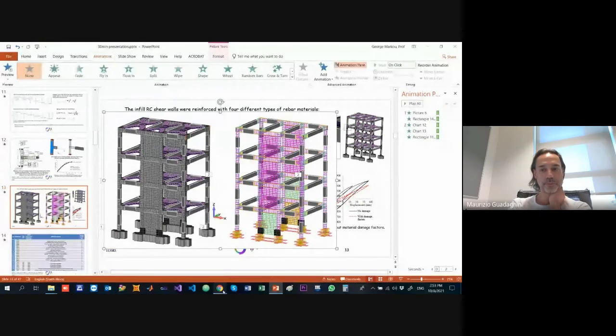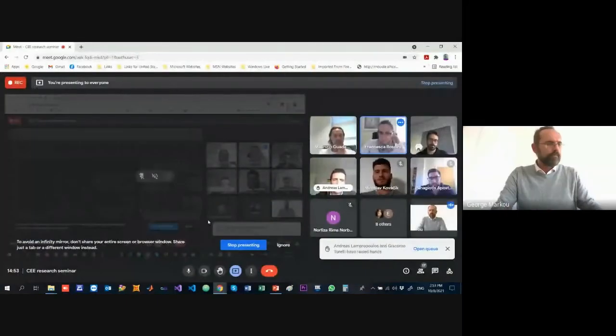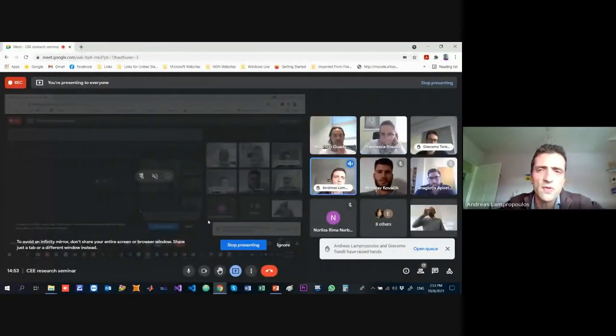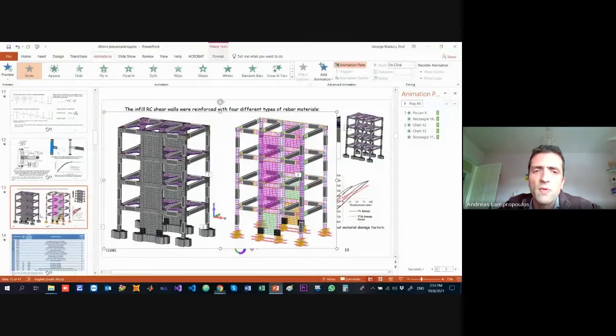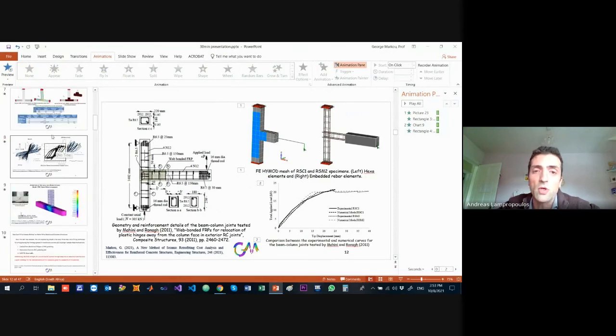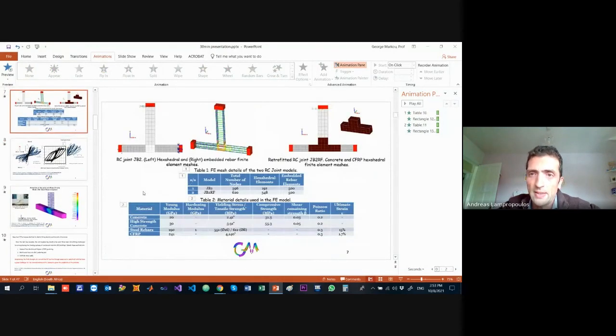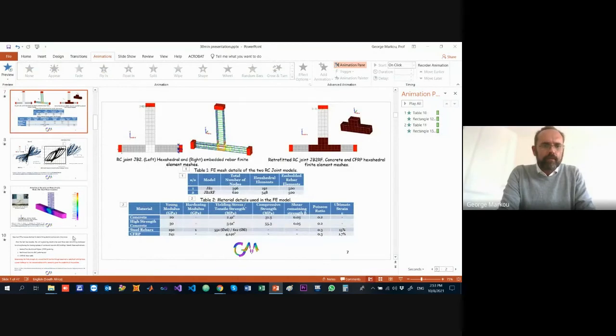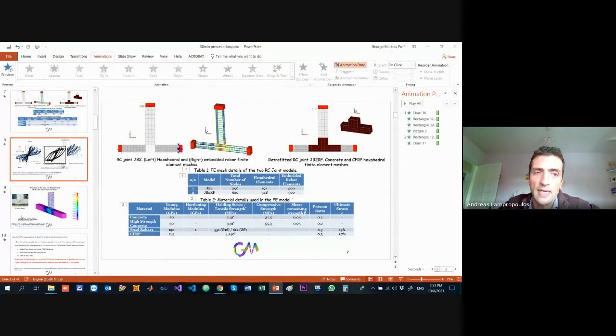Okay, thank you. Welcome. Andreas? Yes, thank you, George, for the very interesting presentation. One question for the modeling of the joints was a few slides before the one you were there. As far as I understood, you simulated the cyclic loading, the degradation due to cyclic loading of concrete, with the damage factor. Am I right? Yes, correct. And did you do the same for steel in this case?